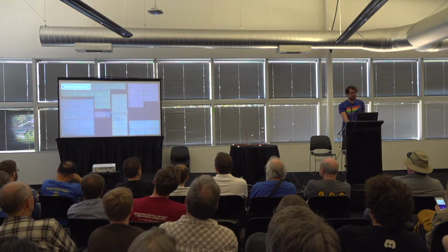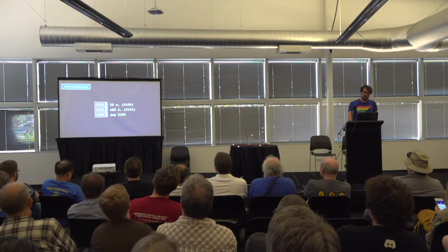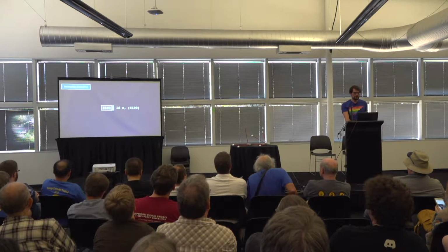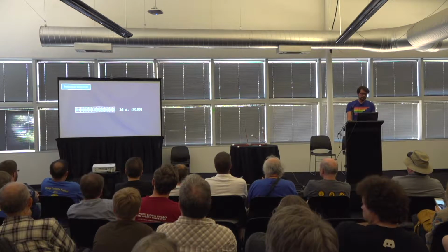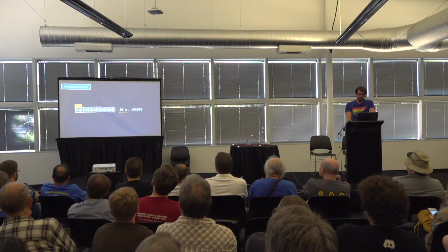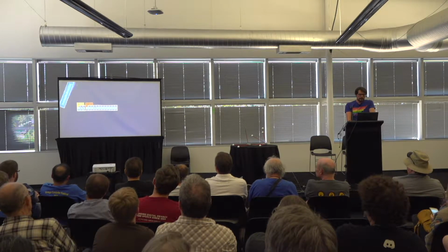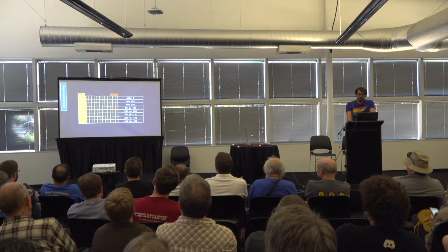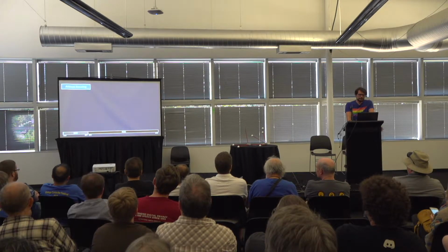We've now seen the instruction set, and in the examples we have seen the codes that represent instructions in memory. Let's look at how the encoding works. For this load instruction, the upper 3 bits are the opcode representing the load A, and the remaining 12 bits are the address. This allows for a total of 8 instructions, but there are more than 8 instructions.